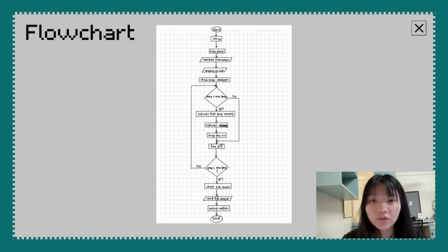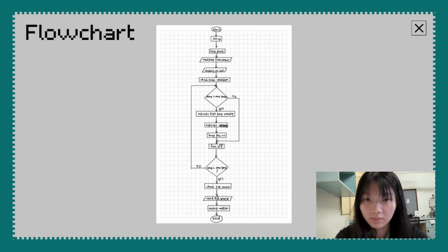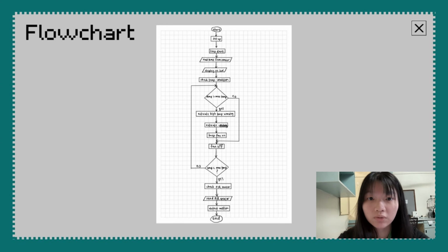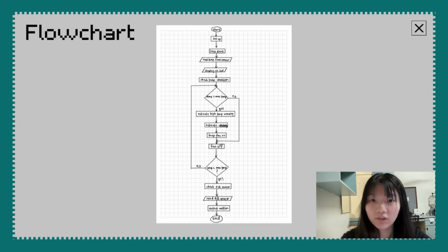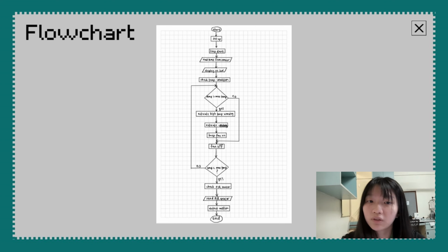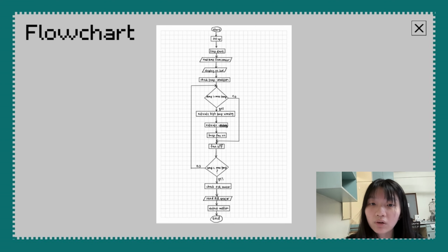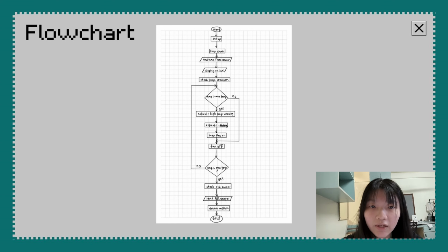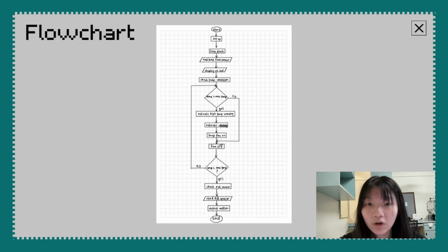The condition used here is, when the temperature exceeds the maximum temperature, a high temperature warning is activated to ensure the user's safety. And conversely, if the temperature does not exceed the maximum temperature, the fan will be switched off. Once the warning is activated, the cooling system will also be activated, and the cooling fan will be left on. After some time, the cooling fan will switch off.